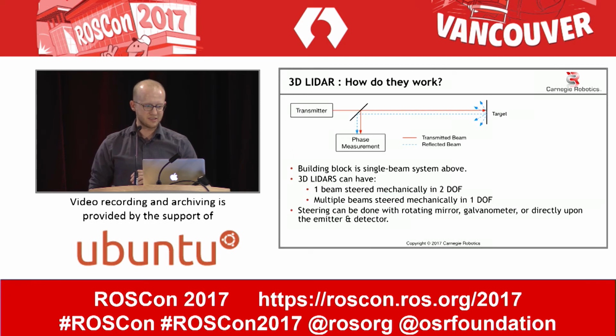So going into some technologies, 3D lidars are fairly simple from an architecture perspective. They're very, very tricky when you get down to the physics of it, but you're basically sending out a pulse of light or a continuous wave of light, and then you're doing some measurement on both your emission and the return of that emission from the environment. Normally these are built with multiple arrays of single point sensors, and you actuate them in 1 or 2 degrees of freedom to build a 3D sensor from a 1D sensor or from a 2D sensor.